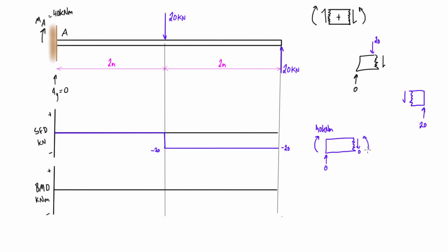And then we're going to have also some internal moment M. Now, talking about these 0 forces here that would form a force couple, even if these were non-zero numbers, we're taking our cut an infinitesimally close distance, or tiny distance away from the support. So even if these were non-zero, the moment caused by this force couple would still be 0, because as this distance tends to 0, the moment caused by the force couple tends to 0 as well.